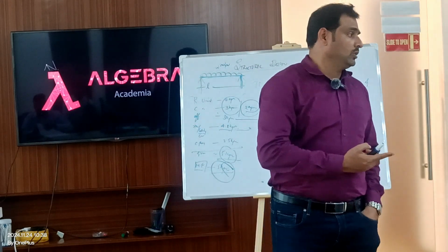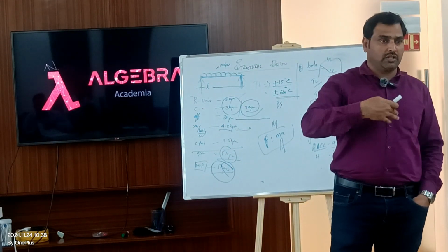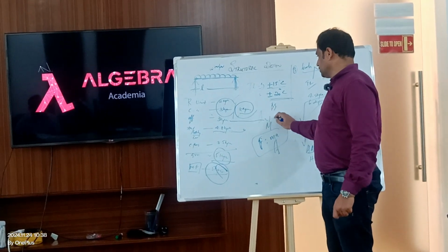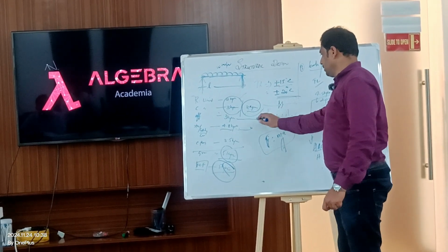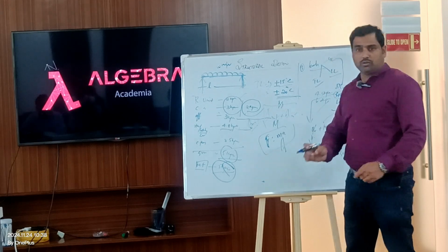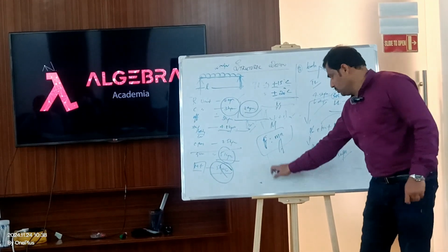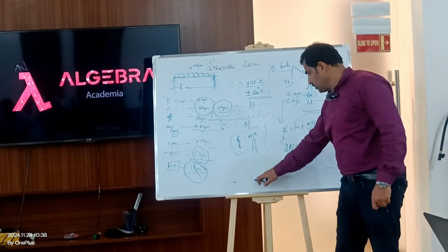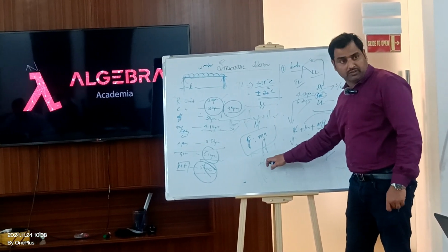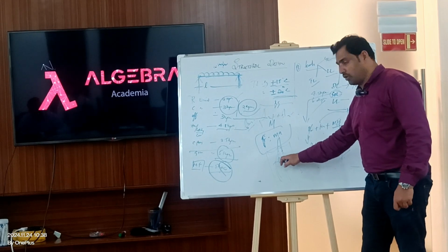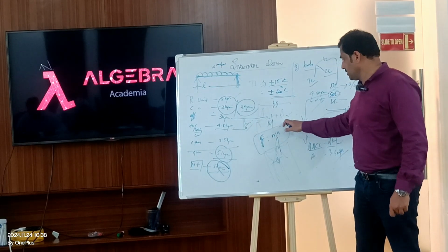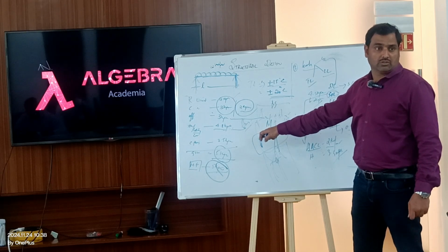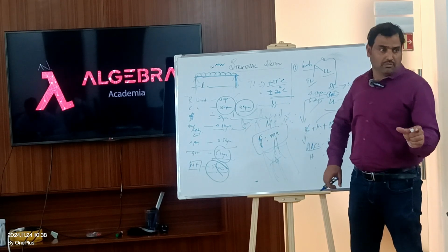That's what I will tell you in the whole new design, because if I say something now, you will be confused. The resultant is the square root of delta m1 squared plus delta m2 squared, which gives the width of the expansion joint. If I have two adjacent towers, this tower gives a certain maximum drift, and the other tower gives its maximum drift. Say, for example, 50 millimeters and 60 millimeters, the resultant might be 55 millimeters. Then I need to keep the minimum joint width at 55 millimeters.